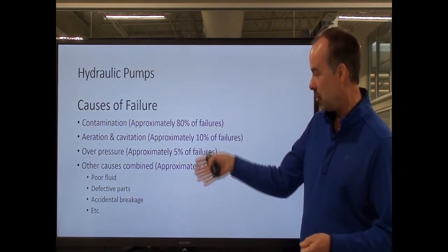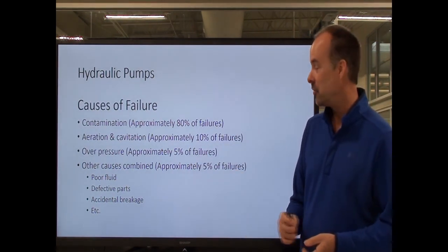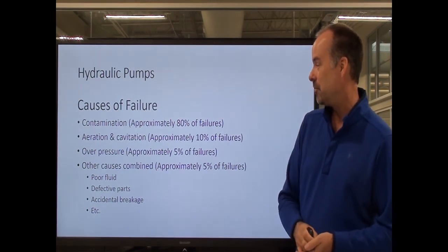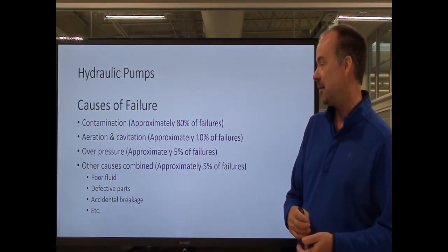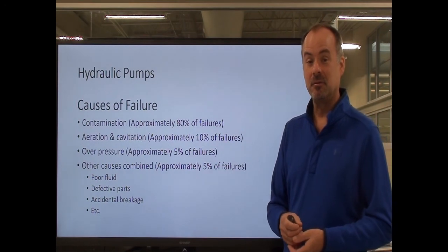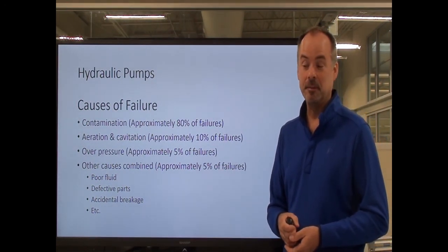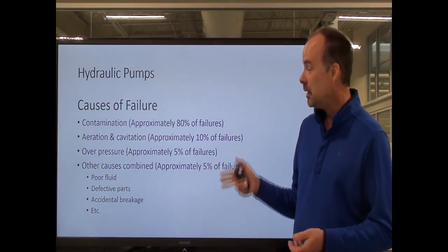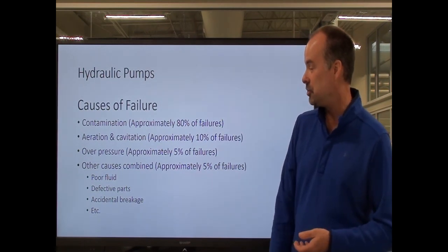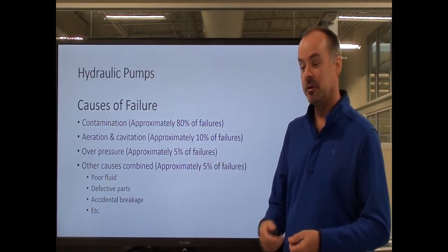That just gives you a breakdown of the failures. But one of the worst failures you can have, and the most common, is contamination. Dirt in a hydraulic system is your enemy. So that gives you an idea of what you might find out in the industry.